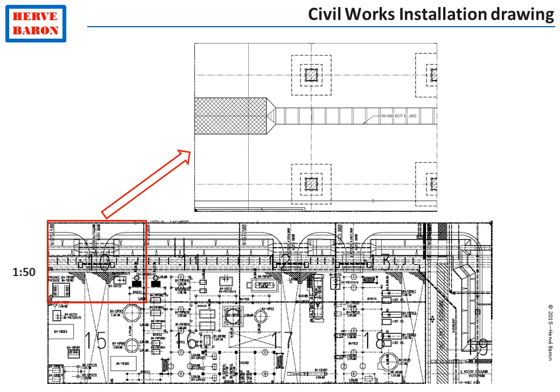Therefore, these area drawings will be subject to revisions, numerous revisions. They will be issued in the same sequence as the works at site. Their first revision will be for equipment foundations only. Then they will follow the work sequence for the installation of undergrounds at site, which proceeds from deep to shallow. The next issue will therefore be for the next layer above the foundations, which is the main headers, such as the sewage header and the rainwater distribution header.